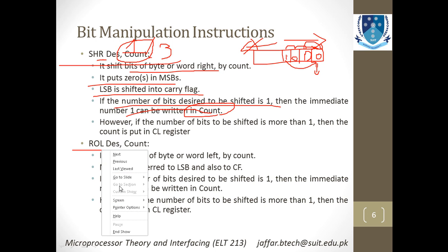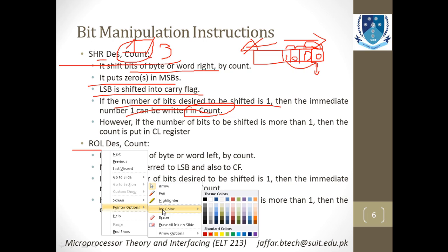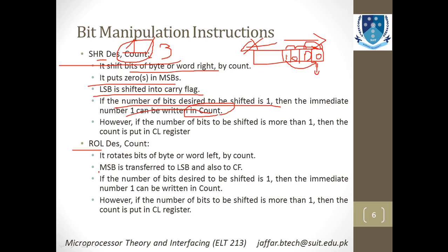There's another very interesting command, which is rotate left. It does the same stuff, but it basically uses the carry flag, the flags actually. This is a little bit different from shifting. It basically rotates the bits. What do I mean by rotates? By rotating the bits, it transfers the MSB to the LSB, and also to the carry flag. So this is another very cool instruction provided by this instruction set of the 8086. It is not that commonly used in the 8086, but it is of some use. So this is another option for you if you want to rotate the bits towards the left.